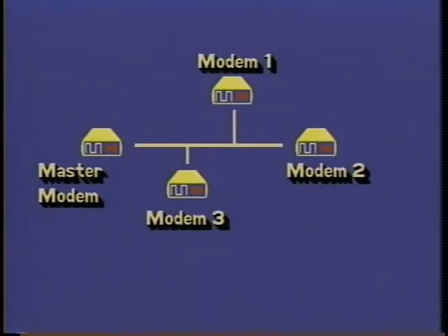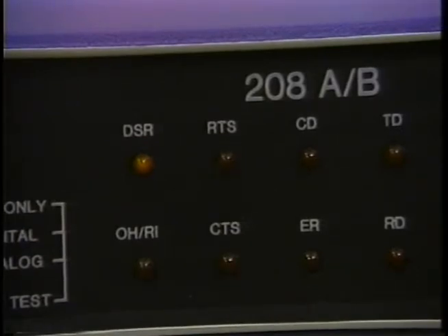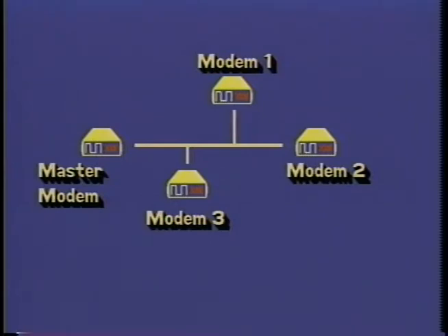Streaming modem disconnect results in a modem shutting off transmission from the attached terminal. The streaming modem disconnect should only be used at the remote end modems on multipoint lines. On a high-speed modem, the terminal should be able to transmit any message within much less than 45 seconds to a minute. If the terminal fails to turn off its request to send after 45 seconds or so, the streaming modem disconnect option results in the modem turning off its transmitter, even if the terminal request to send is still on. This allows the computer to proceed with service to other terminals on the multi-drop line.